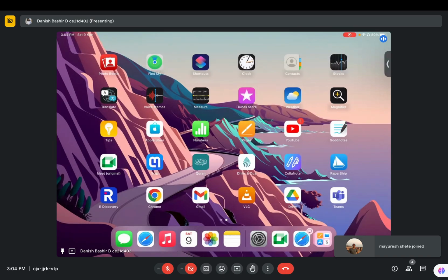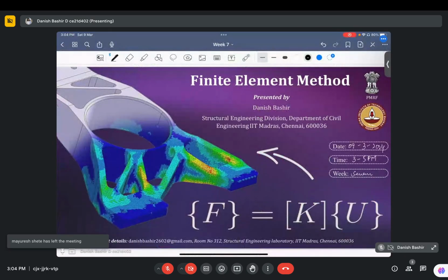If you remember from the last class, for a 2D truss there were 2 degrees of freedom at a single node: one displacement along the x-axis and another displacement along the y-axis. So if we continue that system into 3D, we will have one more degree of freedom along that direction. I thought that's not important. You can do that at your own place. You can see the analysis of a 3D truss as there is only an increase of 1 degree of freedom.